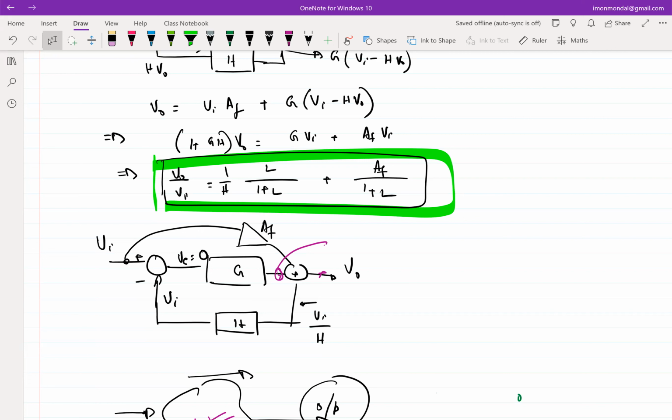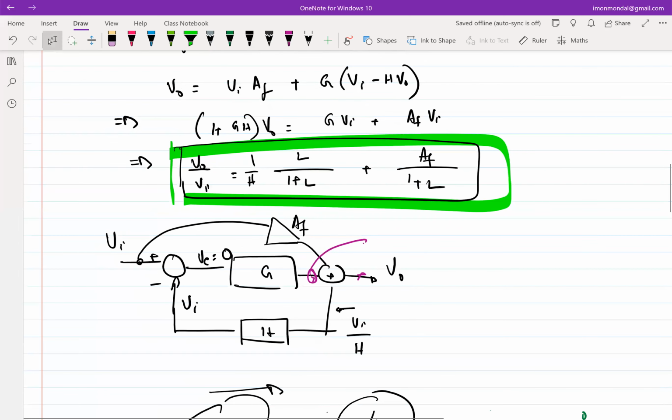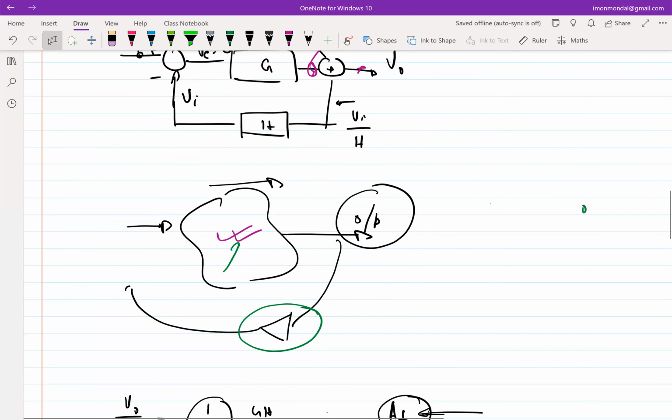So what is that G? In our case, if it's a common source amplifier, G is GM times something. I don't know exactly what G is, but I know it is proportional to GM, because if I set GM to 0, the forward transmission goes off. So I'm setting GM to 0. Make sense? If you do more examples, it will make sense. I'll post assignments you can familiarize yourself with. But it's a very important concept. Again, I am reiterating, so please spend some time on this and familiarize yourself with it.